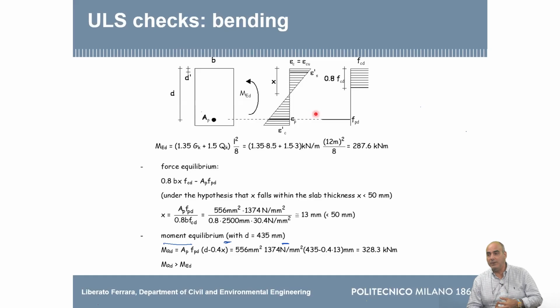Then we know that at ultimate limit state, we assume that concrete is cracked. So this tensile strain part is fictitious when we go into the stress. But we must associate some stress diagrams to the strains. Tensile concrete does not contribute.